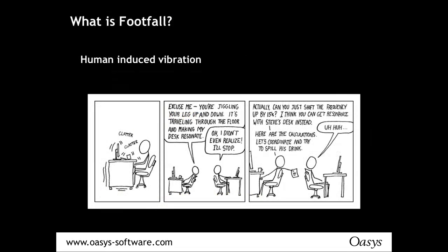It could interfere with the surgeon doing the operation and so on. And we just need to make sure that the vibration is kept under control. So it is human-induced vibration, particularly by people walking around. This cartoon is not strictly speaking appropriate, but it's more about harmonic analysis, which we can do with GSA, and we can look at later if you wish.